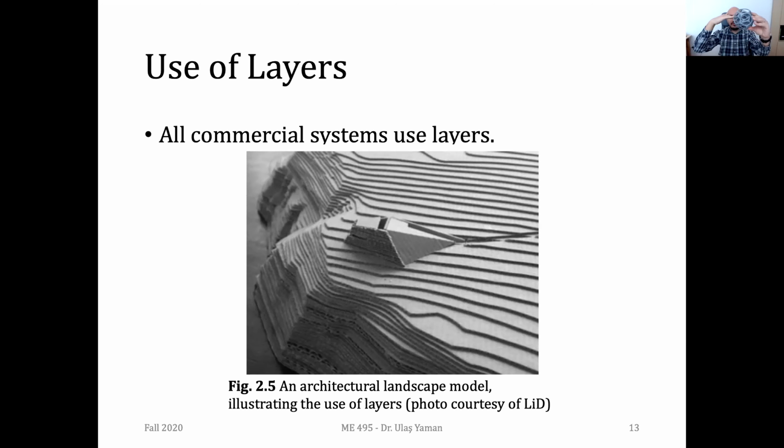Again, you need to do slicing and obtain the slices. Again, whether it's a metal part, you need to do, once again, slicing and obtain layers. And the problem with the layers is that if you have horizontal surfaces, most horizontal surfaces, you will have a kind of a staircase effect. This is actually the biggest problem when you have the slices, layers. So this is called a staircase effect.